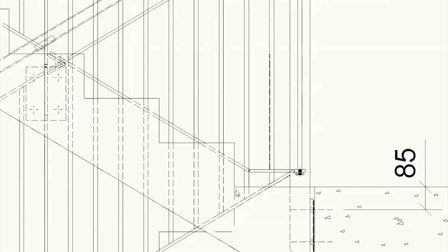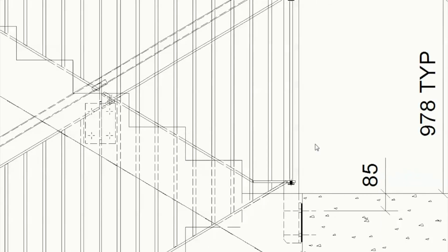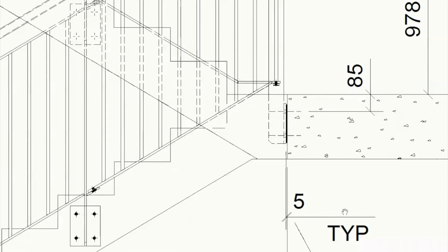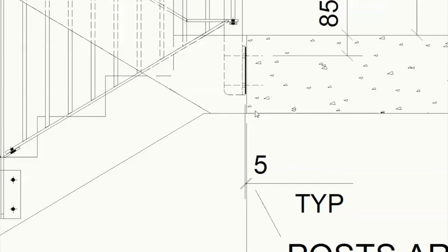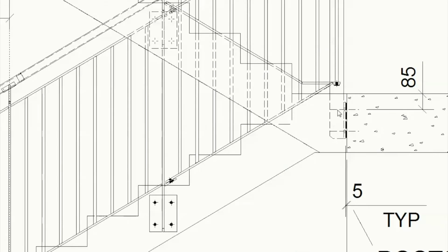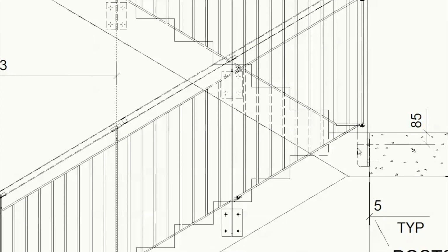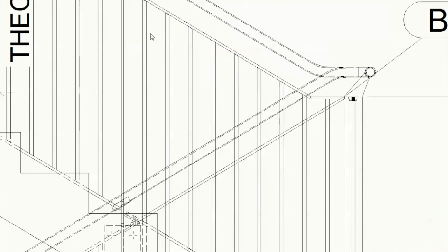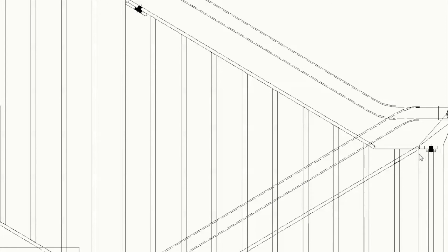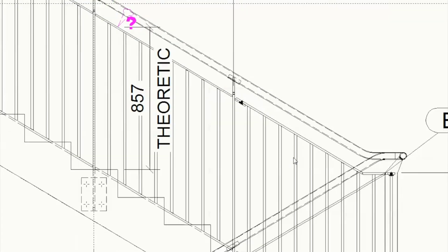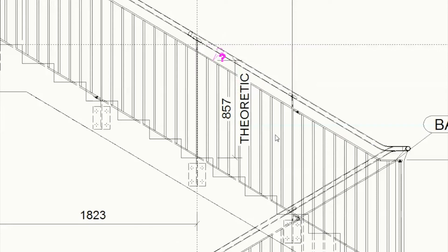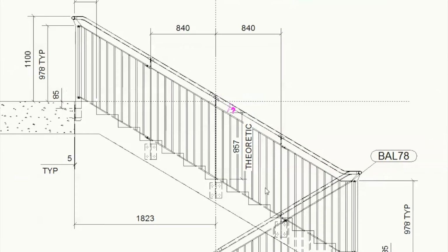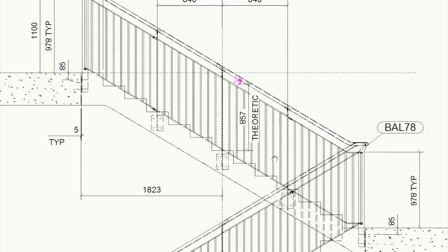Well, this one floats around due to the distance from the tread to the edge of the return voids, and on this particular job I've added a 5mm shim in it, and they'll just put these posts in on loose nuts, and that should give them the option. All these have got slotted holes in the tab plates. That includes on the return posts. So I'm expecting these stairs to fit quite cleanly. I'm not expecting any phone calls whatsoever.